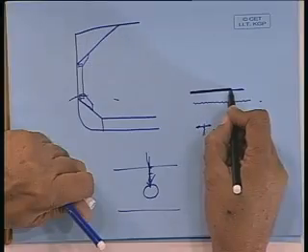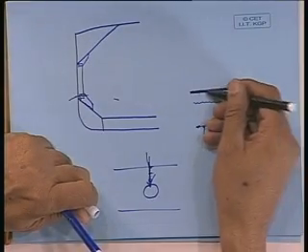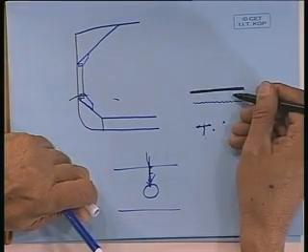And that is why people say that a good quality paint is to be used, because the surface is always under tension and compression. The type of paint, the protective layer which we want, must have more or less the same mechanical properties as the surface of this material. So if this is the surface, and on this you are putting a surface coat here, the interface must be intact all the time.